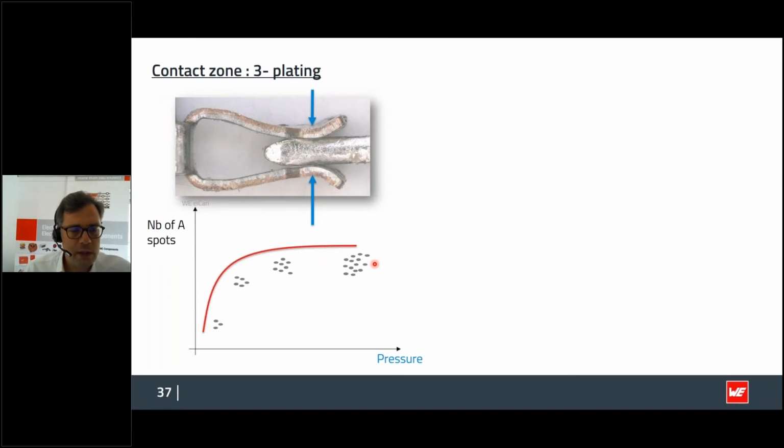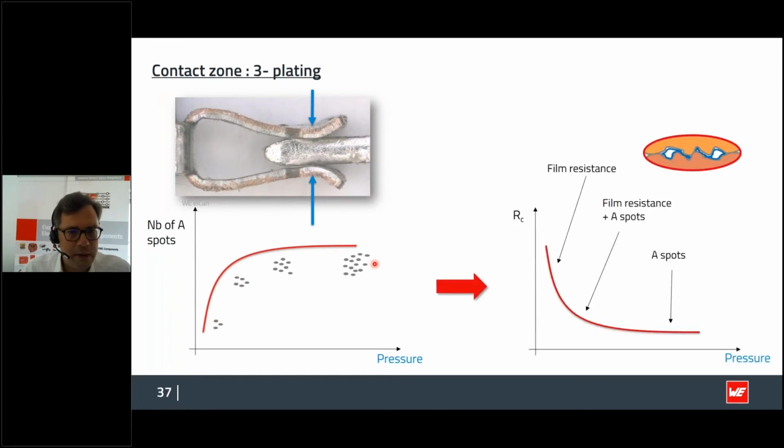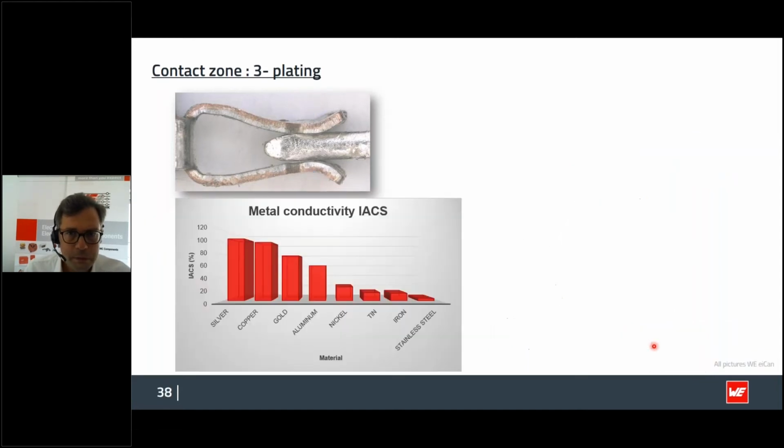More force creates a harsher connection between the male and female side of the contact. That means more abrasion, and this reduces the number of mating cycles. So here in that graph, you can see that you've got an optimized contact resistance, an area that you want to reach, and therefore you choose a material that can meet these required contact normal forces.